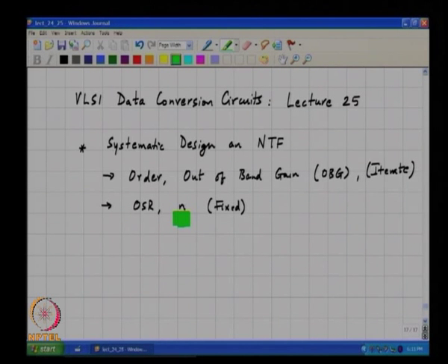So, we can take it the other way around and say reducing n by a factor of 2, which means you reduce the number of levels you have by a factor of 2, will only reduce the SNR by 6 dB, and that can be easily fixed by doing what?